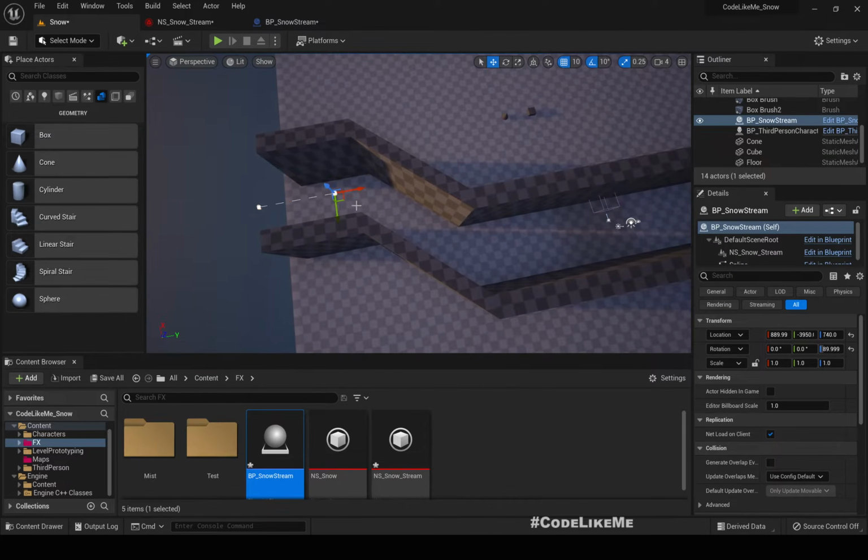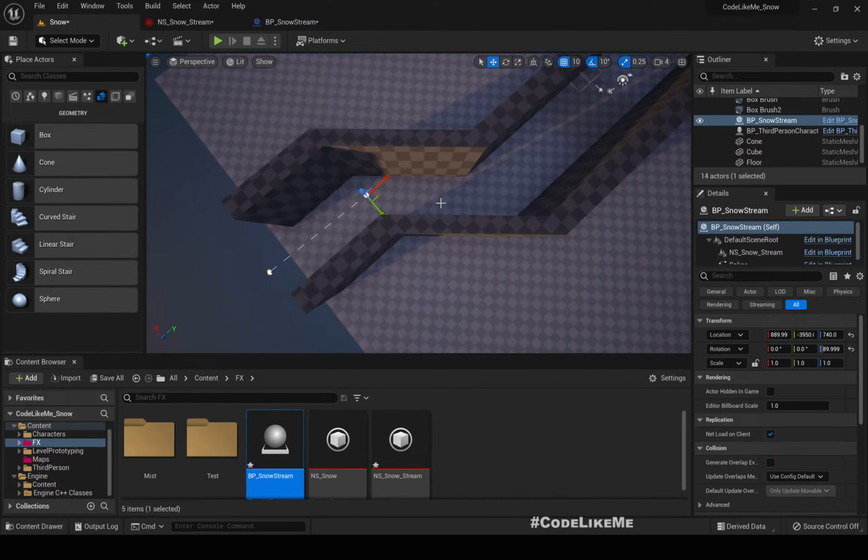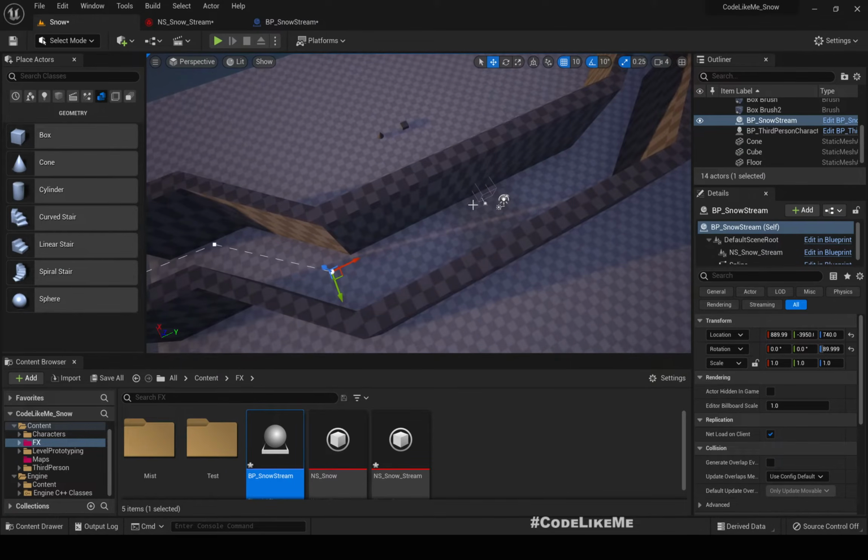and so what I'm gonna do is I'm gonna set this spline along this path. So after selecting one of the spline points, if you keep Alt pressed and drag, you can see the point is duplicated, another point is added, and just like that you can create a path like this.